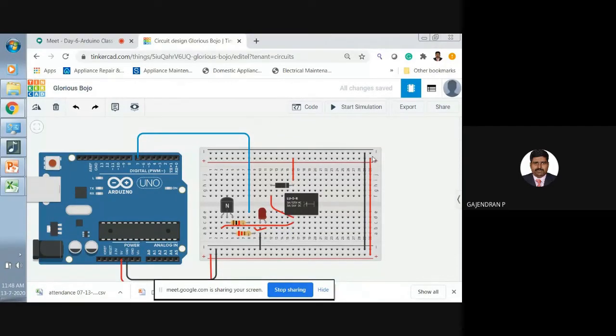So this is VCC 5 volt. So 5 volt goes to the cathode terminal. Then the other end of the coil will receive the negative, so there I need to use the anode. It must be in reverse bias mode. I will explain why we are using this diode later. Okay, so now the control circuit wiring is finished.